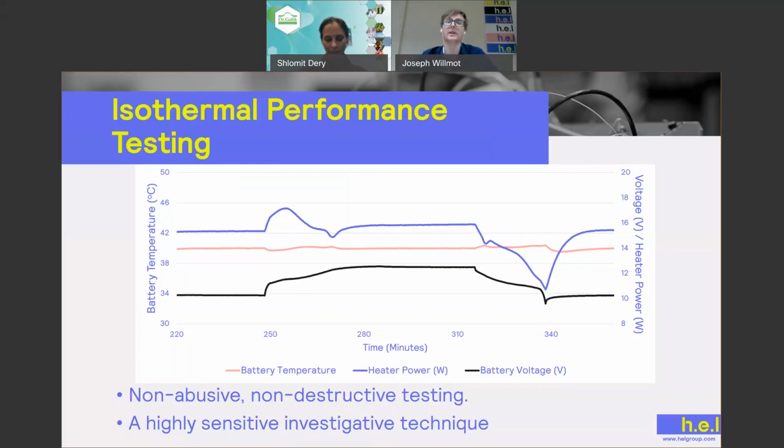In the chemistry world, that would be mixing two compounds together, two chemicals together, measuring the energy released from them to understand what reaction has taken place. For batteries, we know what reaction has taken place. For lithium-ion batteries, we want the lithiation and delithiation of your anodes and cathodes. So we know the reaction that's taken place, but we want to quantify the energy to ensure that we're capturing the entire energy of the discharge and charging of our batteries or cells or battery packs, etc.